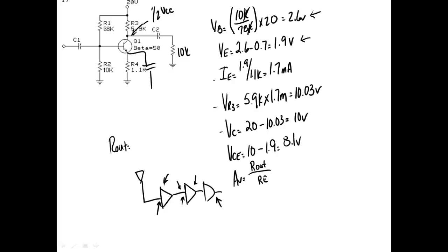In fact, in radios, if you look at the schematic, odds are they don't use a bipolar transistor, because with bipolar transistors we can't get an extremely high input impedance. When we get into FETs, we'll learn that. So most of the time the input amplifier is a FET. We'll start off not bypassing them, and as we go along we'll start bypassing them, and eventually we'll get an extremely high current in. So that's why we go through amplifiers.